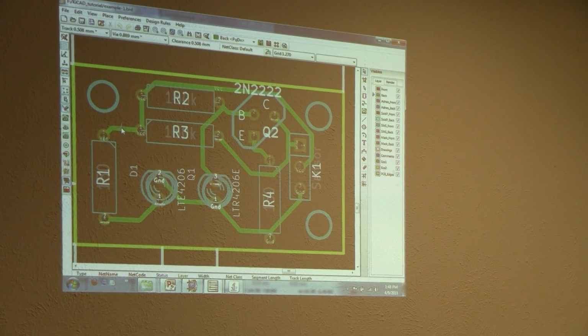All right, so there's our wiring. It's ready to rock. So everybody sees the wiring, okay? Now, see this circle right here? That's my clearance circle. Do you see how it's touching the edge of the board? That's where I got the violation.